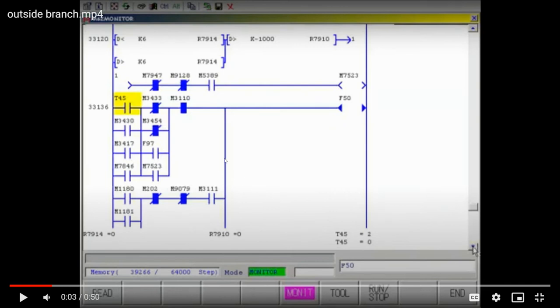Another comment that I have is being in remote connection. In this case, it might be easy to figure out because we need to make these two signals on. But keep in mind that if we have a pulse, meaning a transition where the signal comes on and off, you won't be able to do it remotely or see it remotely. What you can see on the machine screen is a refresh every 10 milliseconds. So if the event occurs in a period less than 10 milliseconds, you won't be able to see it.